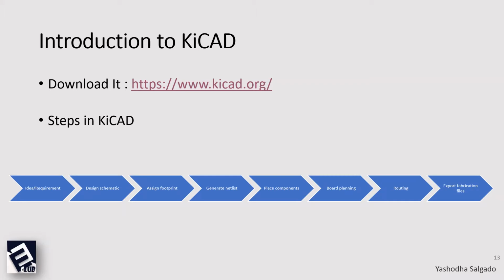And the next thing is place components on the PCB and board planning. I will explain each step one by one when doing an example. Just keep this in mind. And then routing, and the last one is export fabrication files.